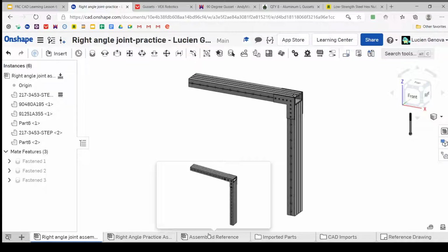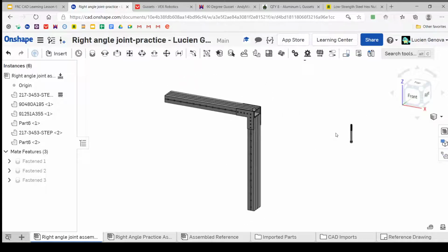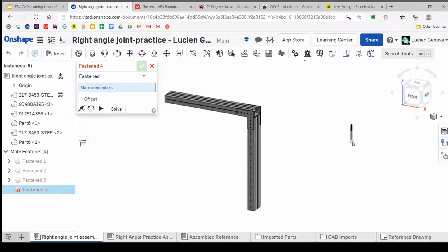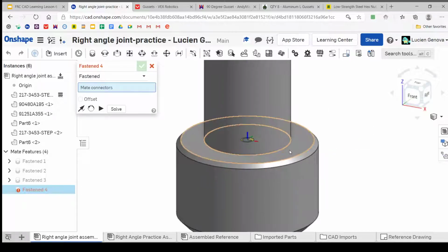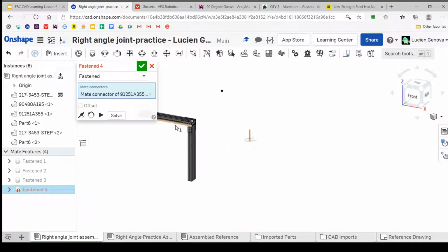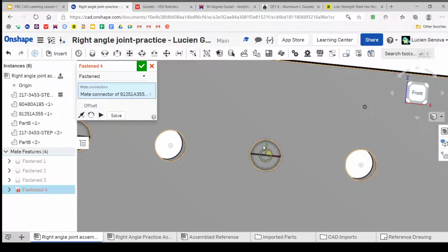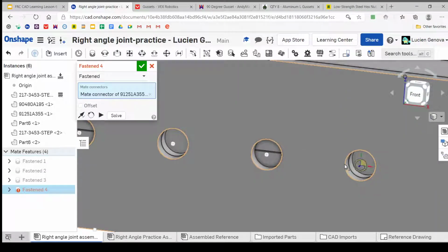You can see here it pretty much matches already. But I think the bolts are sort of implied. But in real life, you need them. If you were giving this for assembly, you would also really want to have these bolts. So we're going to mate. M again, and we're going to click the bottom face of this bolt here. Again, there's multiple ways to get the same point, but we just want the bottom face there. And we'll click one port where the holes go through, so it's not going to be that one, it's just going to be where the holes match up. So we'll click this one for now.